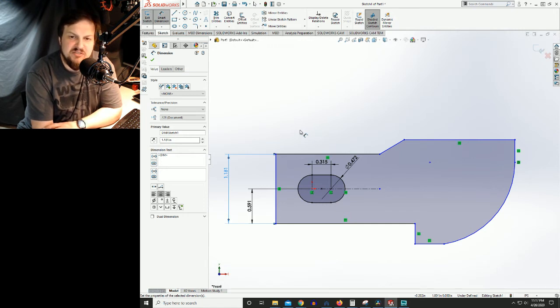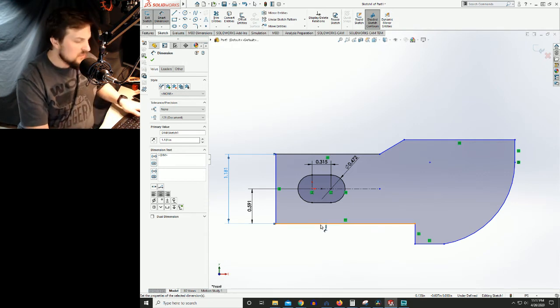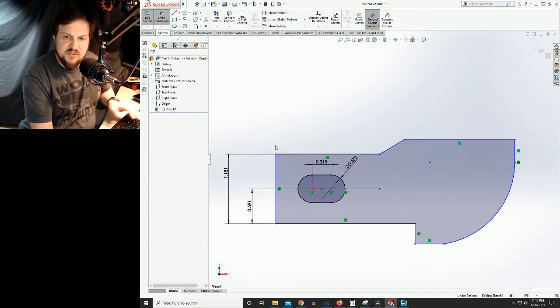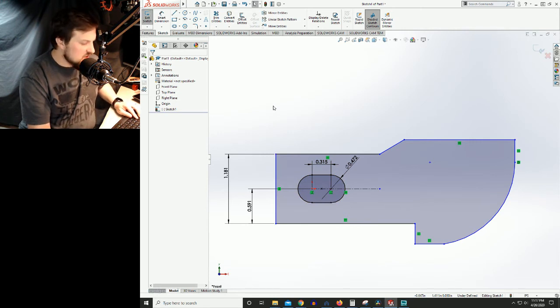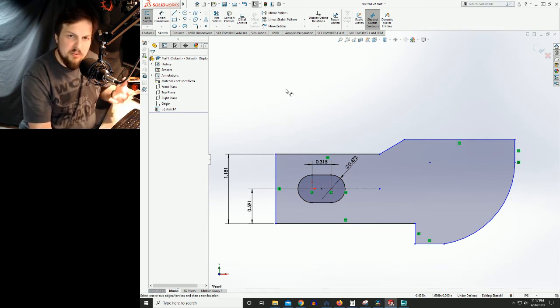You want to be able to define a line in space prior to changing anything about that line other than spatial representation. So I wanted to lock this new sketch, around this old piece right here, this slot, before I started modifying it. That just locks it in space, makes sure that I know where all my stuff is.